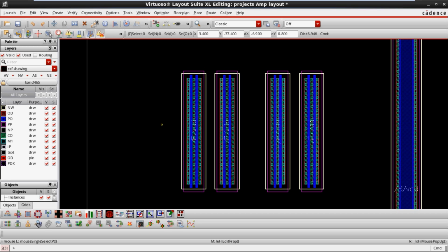Okay, so we have some kind of limitation, some kind of RC extraction they have to do, right? So some tolerance value will be there. So based on the schematic designer's opinion, we can go for a common centroid also, and we can go for interdigitization also. So now I am going to do the current mirror structure with an interdigitization based pattern.